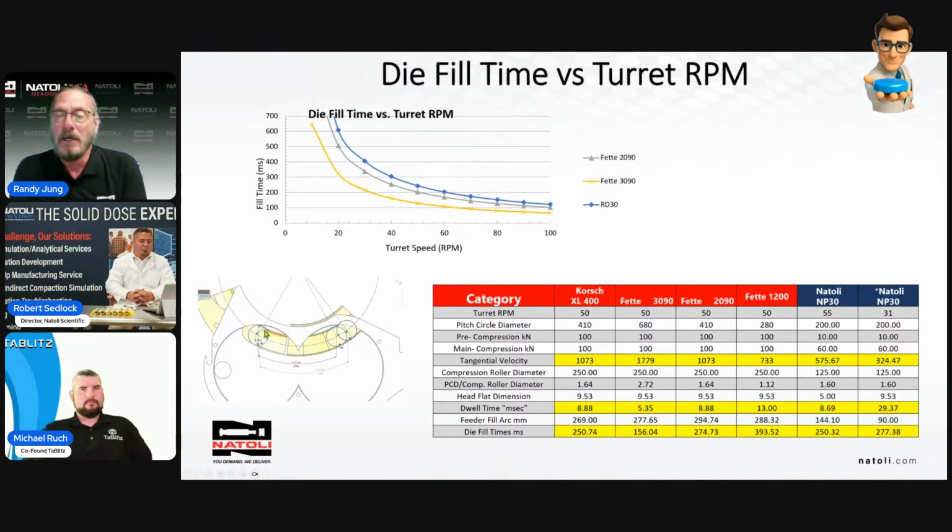Fill is done. You see 2 circles on the right. So you see the circle. That's where this particular machine, that's where its standard position was. It filled from those 2 dots, the one on the right and the one on the left. And that was its fill stream. And they still weren't getting the weights they wanted. So we redesigned the fill cam so we pull down sooner and faster. So now I have a longer track to fill that die, and I've pulled down at a higher speed to get more natural vacuum to pull that powder down in the die.